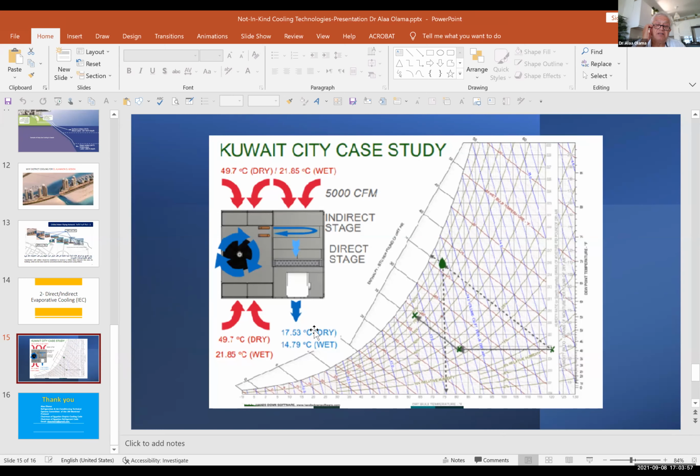So if we are starting to design a new system, taking in mind COVID and the problem of cross-contamination, a full fresh air system such as this one, added to it a DX coil or a chilled water coil, will get the air going in one direction, reduce cross-contamination to a minimum, and also reduce energy consumption.